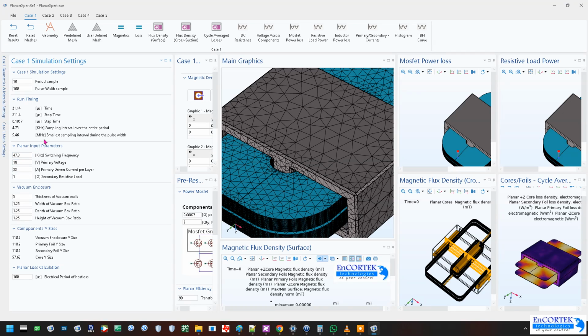And we go see if we are having any issues with overshoot and high frequency ringing, we would like to see that information. That depends on how many steps you do with the pulse width, which covers those fine data. So for a faster simulation, I will just put the minimum.